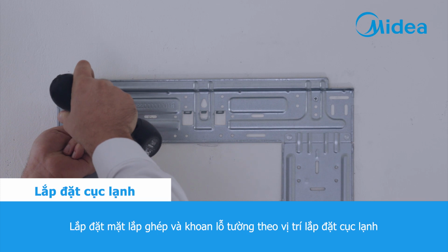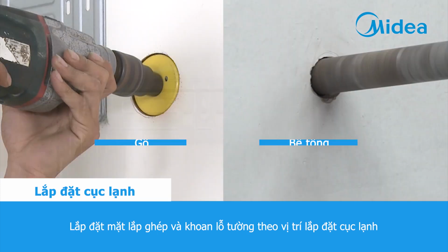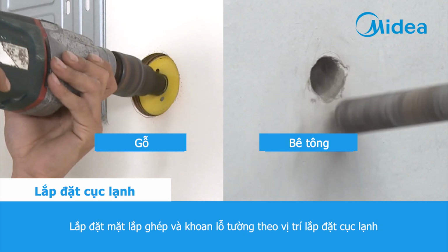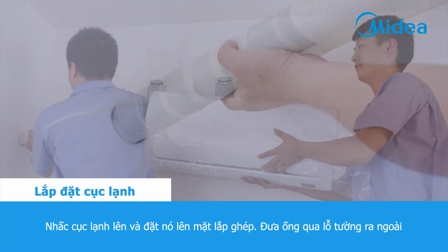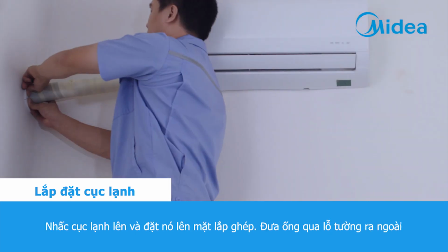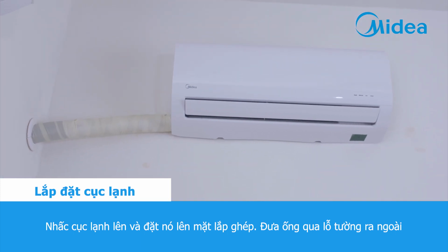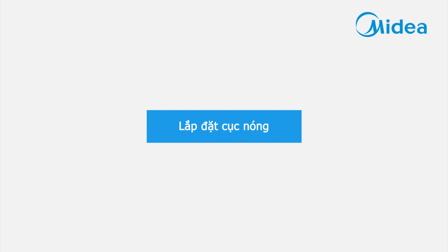Install the mounting plate and make a wall hole according to the installation position of indoor unit. Lift the indoor unit and put it on the mounting plate. Insert the pipes into the wall hole to outside. Installation of outdoor unit.